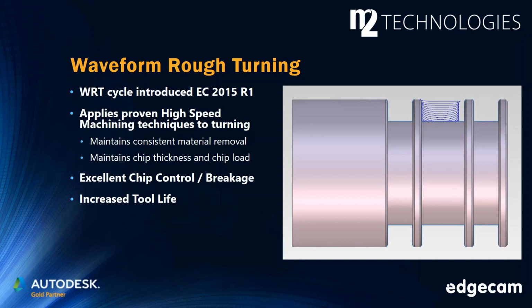The example we have shown on the screen here has a simple groove, and in that groove you can see how the tool rolls its way in and rolls its way out. Compare that to the typical approaches of pushing a tool straight in with a typical plunge groove, or maybe a side groove technique where the tool plunges in and machines sideways. While those techniques do remove material, they introduce cutting stresses that can be very difficult in some materials or some part shapes, and certainly not ideal for a tool.